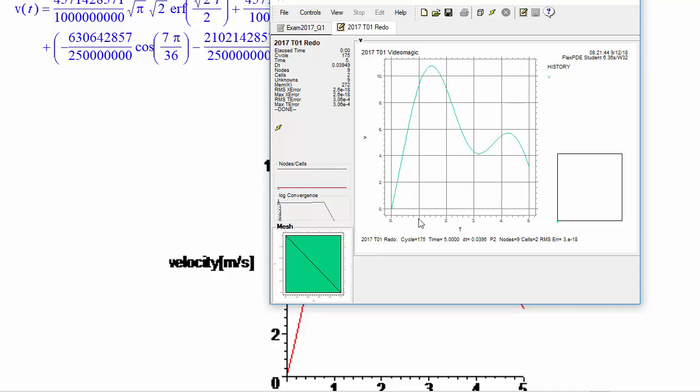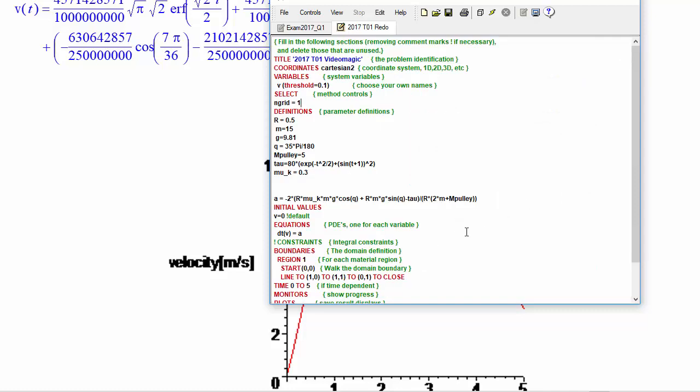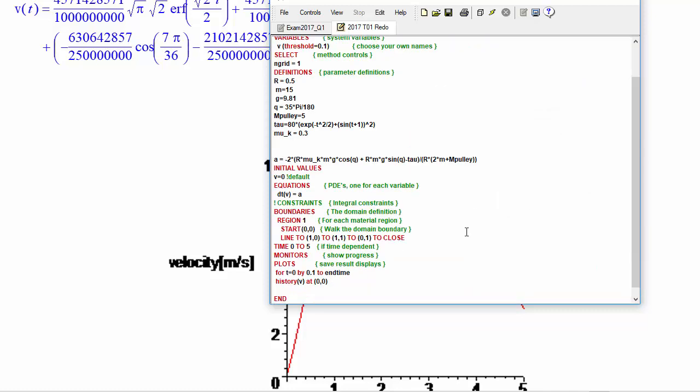If you wanted to get what the velocity was at the end, then you could use the summary syntax. So maybe we'll put this in caps to make it easier to see. But again, Flex is not case sensitive. So now let's see, what is eval v 0, 0, 0? No, that's not it. It's not eval. What is the syntax for that? Ah, report eval.